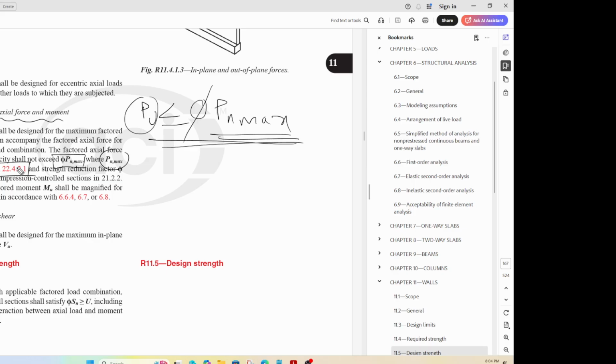If you have designed a column, then you would have seen that section. Pretty common when it comes to calculating the axial load capacity. For example, if you have a column, that column has all the ties, then the code says use 0.8 times P0, and then the P0 is something like this equation.